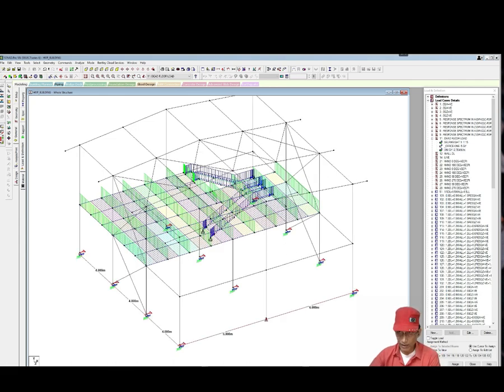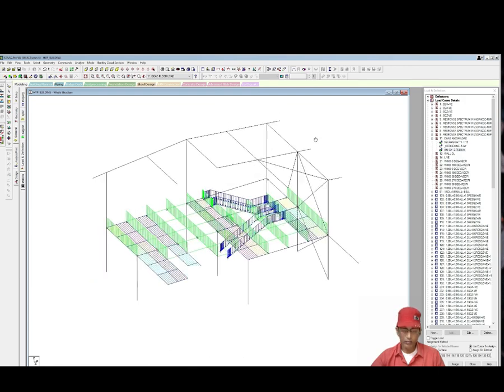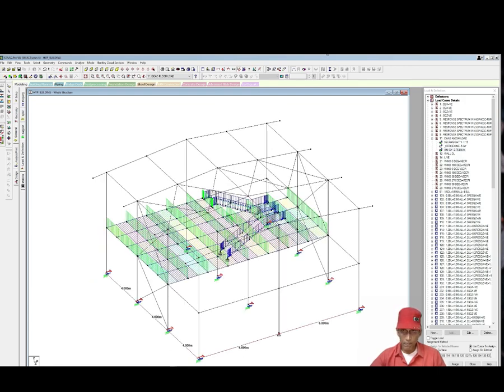So we had calculated the weight of the roof sheeting as 45 kg per square meter, that is 0.45 kilonewton per square meter. So this load would be carried by the gable rafter as per their tributary width. So this gable rafter has a tributary width of 2 meter. This is 4 by 2 is equal to 2 meter. This interior rafter has a tributary width of 4 meter.